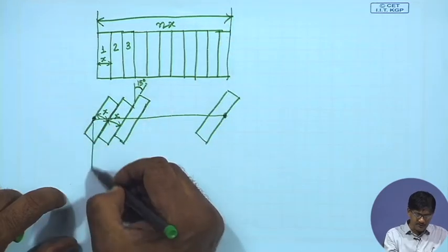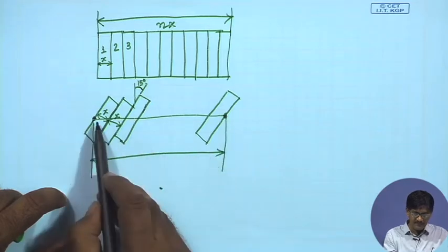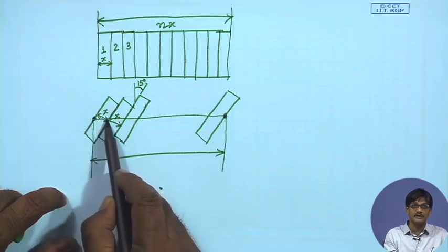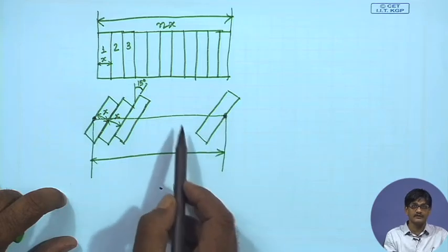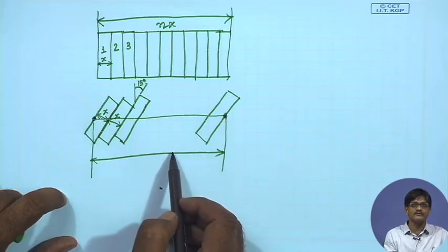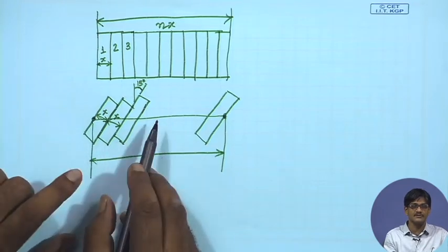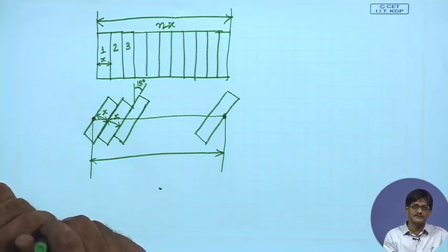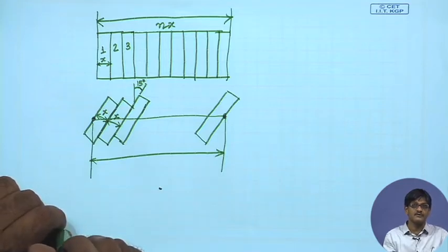Will this be equal to n x once again? Obviously not, this is x. So, it will be slightly more than x, and that multiplied by n will be definitely higher. The moment you find out this increase, you have found out the difference in the diameters of helical gears and spur gears. Mind you, we are talking about pitch diameter up till now, pitch diameter.